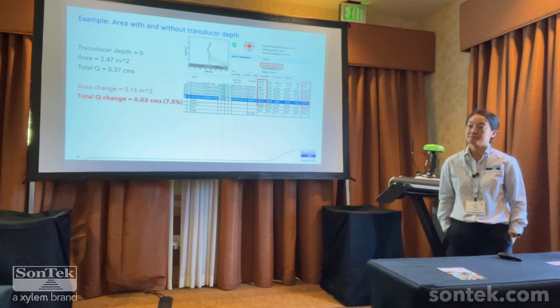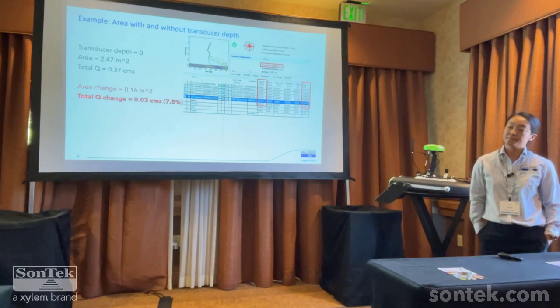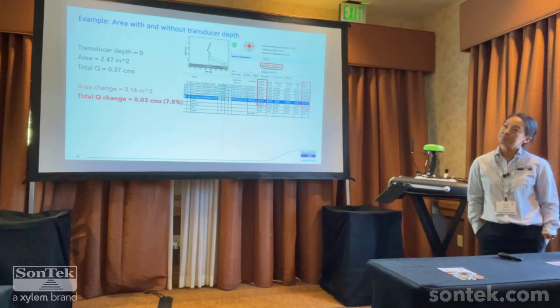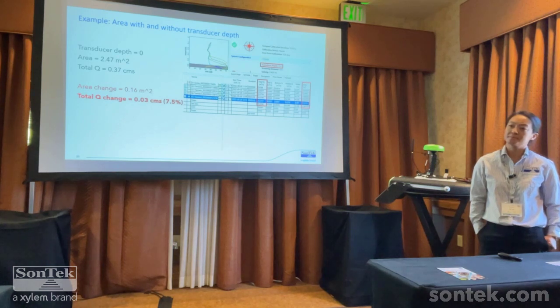And tomorrow at, I think it's 1:30, I'll be talking about a site where we measured in a compound trapezoidal channel that's concrete, and it was moving. Do you remember how wide Prado Dam's site is? We got maybe 200 to 300 feet wide, moving at like 10 feet per second, 8 to 10, I think. We got an okay measurement. It wasn't outstanding, but it was a decent measurement.